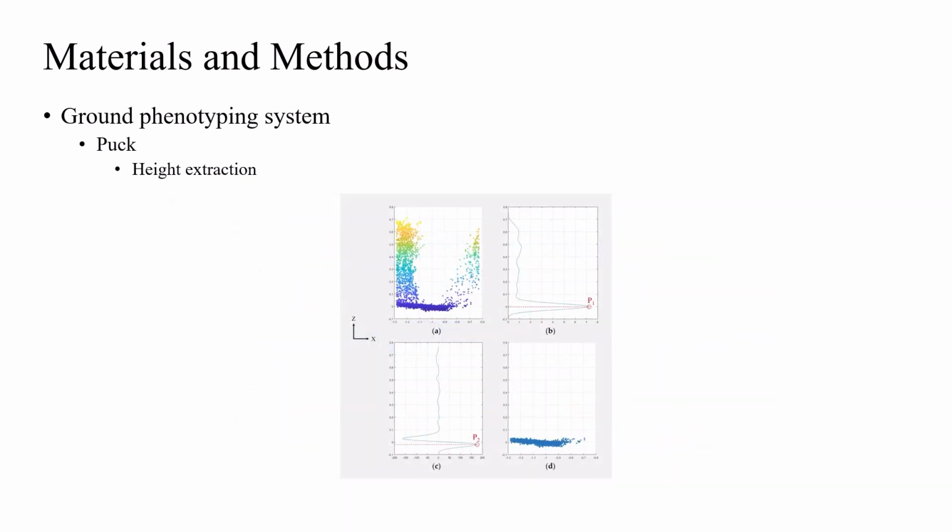In the third step, the z-value kernel density and the first derivative of the kernel density curve were calculated for each alleyway point cloud. Assuming ground points followed a normal distribution along the z-axis, the first peak in the kernel density curve, P1, represented the mean of the distribution.